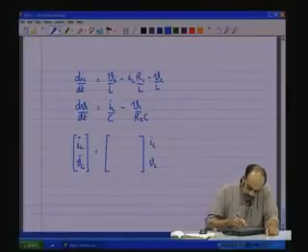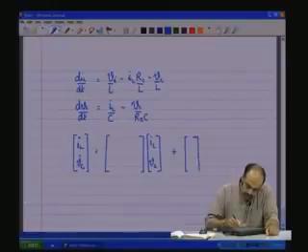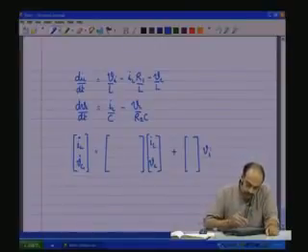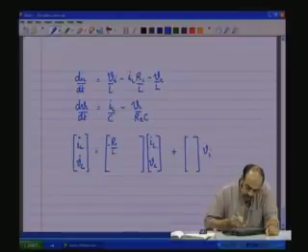We see this is the state vector X plus we have to write the input scaling matrix, and there is of course only one input, which is Vi. So IL dot equals IL is multiplied by minus R1 by L, minus 1 by L into Vc.